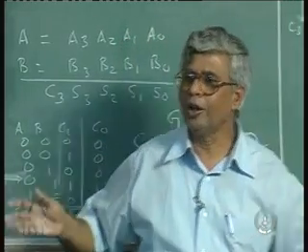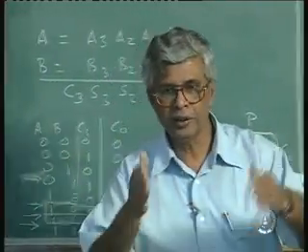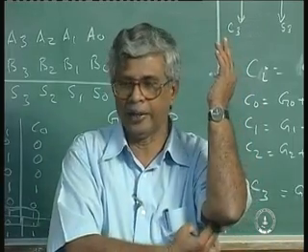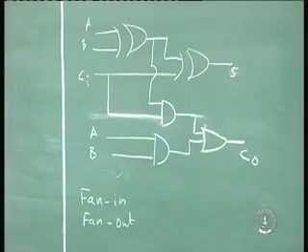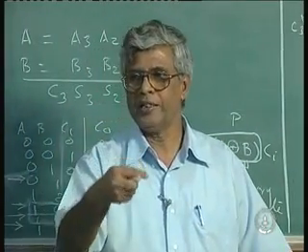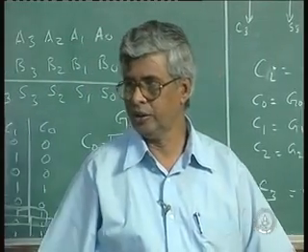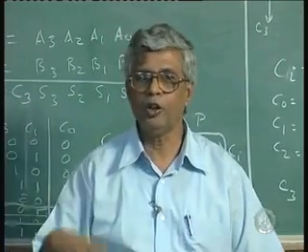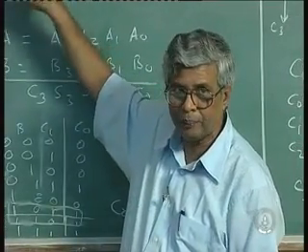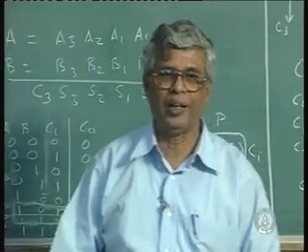But let us not go into all that, we will talk about at most carry look ahead connected in propagation mode. Suppose you want to build a 16 bit full adder, I will probably do it with 4 carry look ahead adders, C3 feeding into the second stage, C7 feeding into the third stage, C11 feeding into the fourth stage. That is good enough for this class. But I wanted to introduce this, so basically even though carry look ahead, as I said, is the example I use for speeding up, this is something you should be familiar with at a conceptual level.